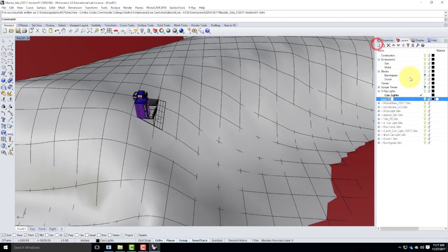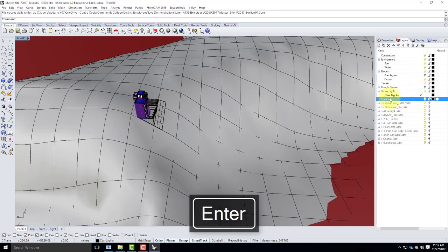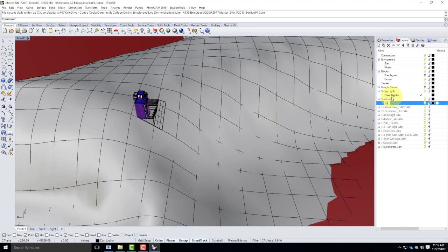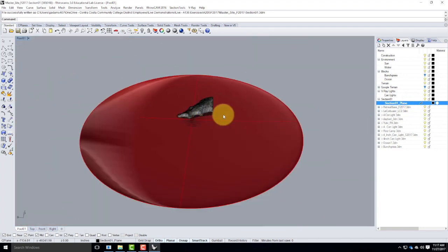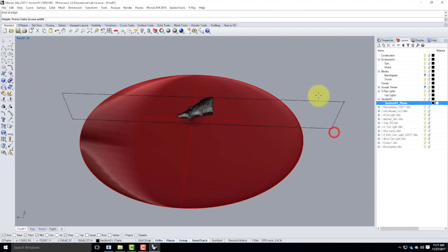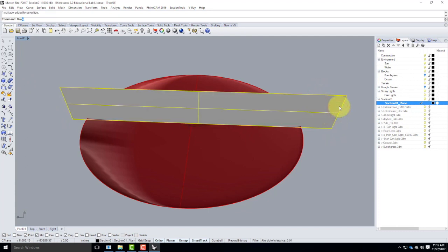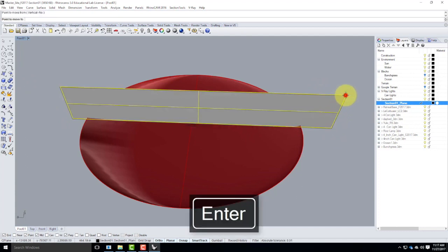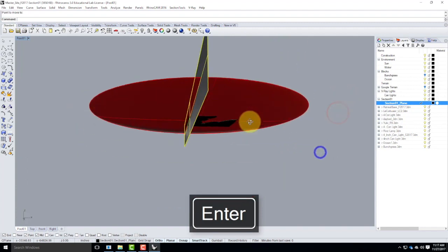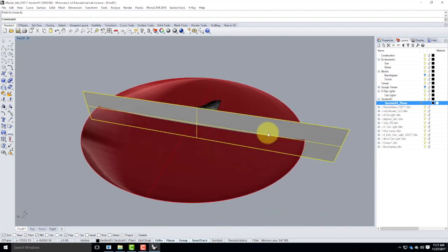I'm going to create a new layer called section. And I'll call it section 01. And then below that, on a sublayer, I'm going to create the section 01 plane. And this plane is just a really large horizontal plane that fully intersects with all of my objects. So let me create this vertical plane from there to there. Let me move it down a bit. And so that definitely intersects my whole drawing.